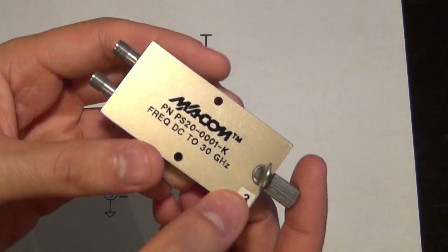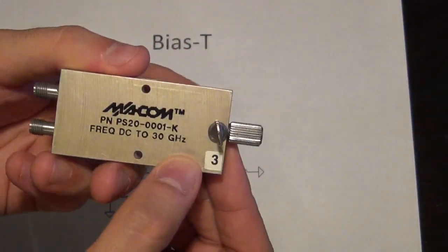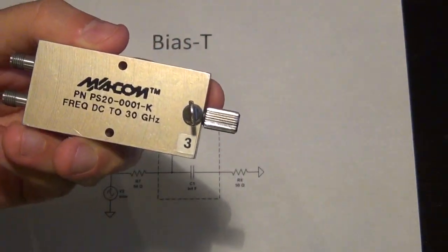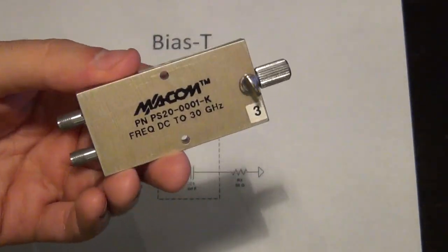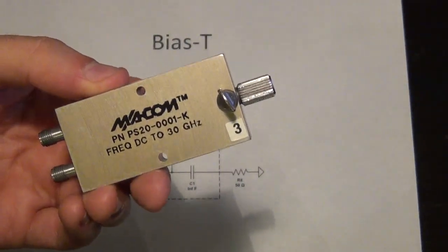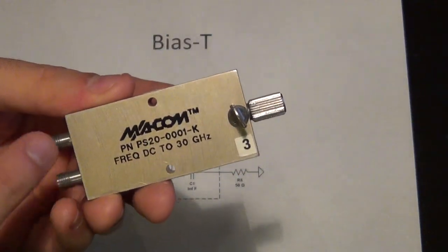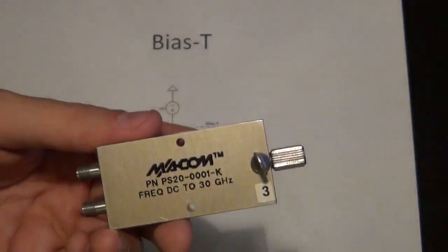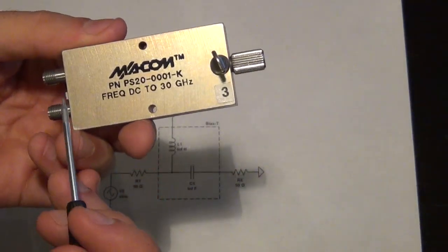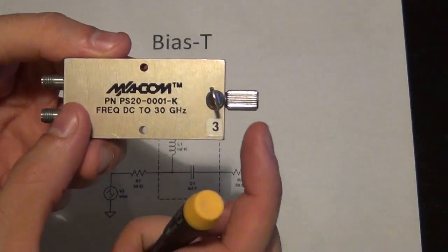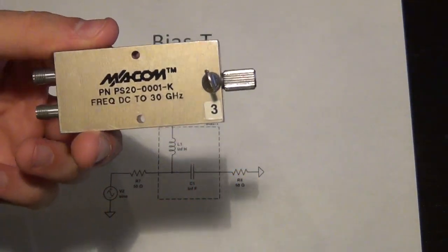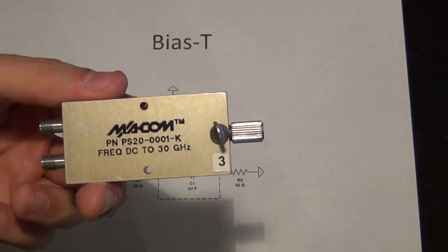You can make other interesting passive components. This is a phase shifter that works from DC to 30 gigahertz. Now the best way to achieve phase shift is to change the physical distance between these two terminals. So how can that be achieved? So what I mean is that if I have a cable and I make a cable longer and longer and longer, obviously the delay through the cable changes and it will accomplish a certain phase shift.